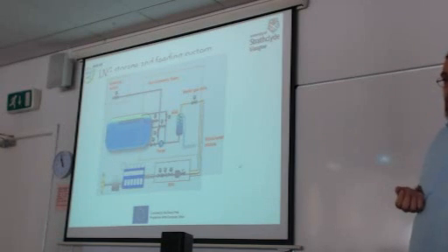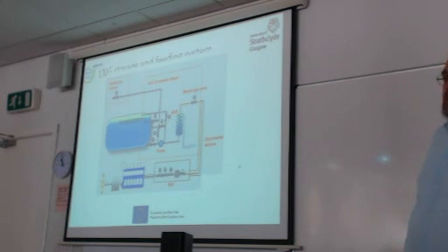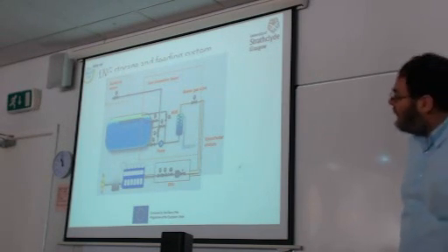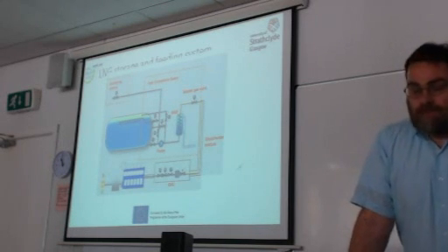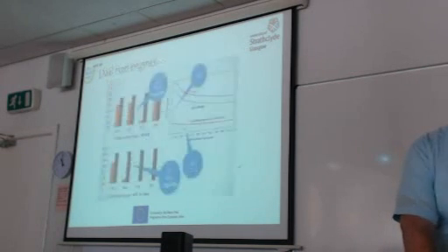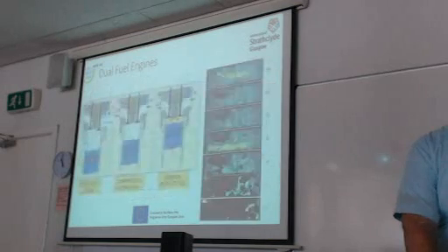And of course, we need to take into account the safety requirements and classification society requirements. Double wall piping is required, and ventilation between the piping is required. We need to avoid issues from natural gas leakages or LNG leakages, which are very dangerous. But research is in progress, and the manufacturers, I think, see the application of LNG as first priority. I also heard that the Japanese government put that also as first priority for Japanese ports. So there is huge ongoing discussion about the future of the application of LNG on board ships. If you have 1-2 minutes, I can answer any questions.